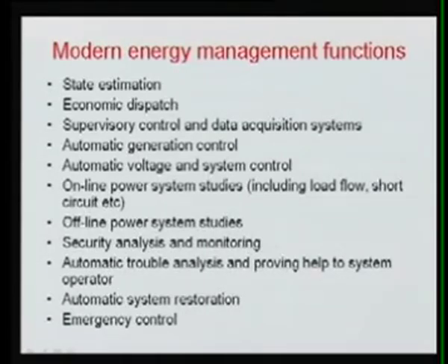Now I can summarize here the various energy management functions, EMS. First, that is very important, is your state estimation. Then we have software related to economic dispatch. Here in the economic dispatch, there are various types of economic dispatch programs. It may be your real power dispatch, it may be your reactive power dispatch, it may be your emission.